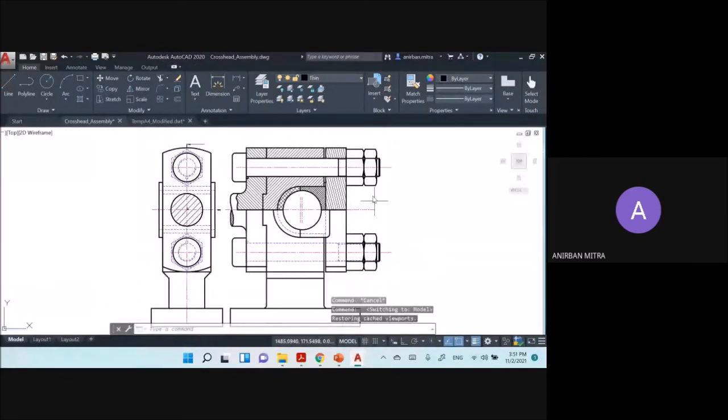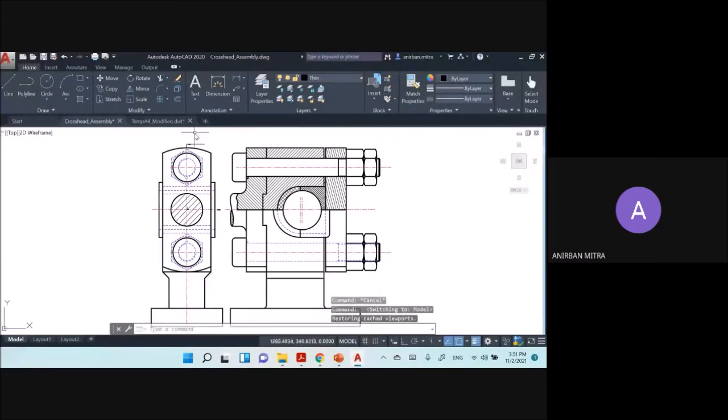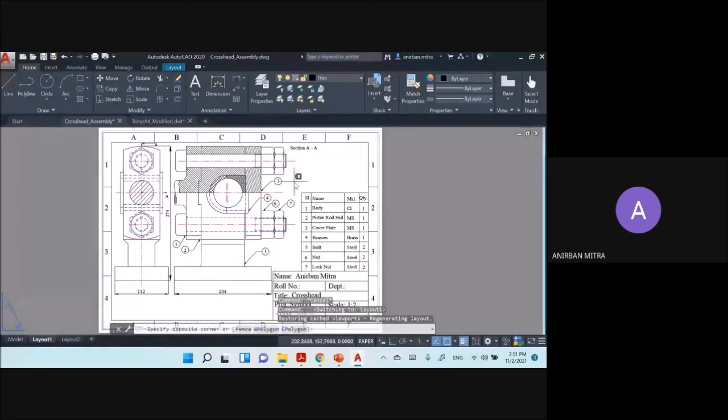The original drawing is actually in the model space. So it has been drawn in model space, but then we have used a viewport like this to show it along with the margin and the title blocks. So if you now take a printout of this, it will almost be like a drawing sheet that can be preserved.